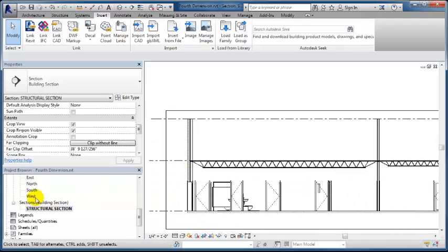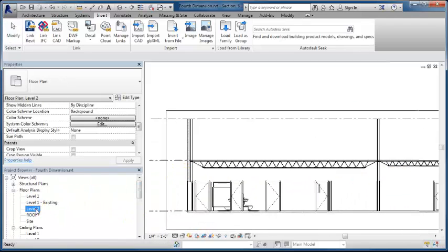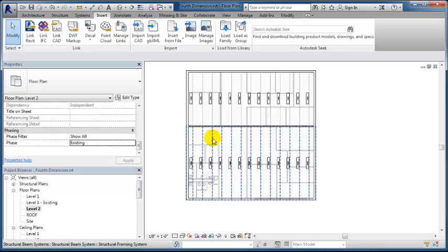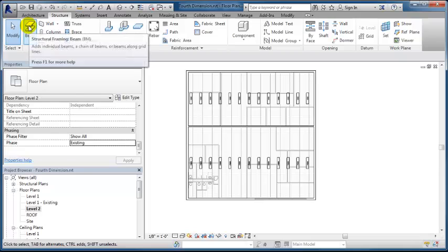Okay, so on the sides here and here, we would need to have an I-beam supporting those trusses. So I'm going to add those elements to our level 2, and for now I'm just going to change this to existing as well, so I don't have to keep switching it over. And we'll go under Structural, and this time I want to create a beam.